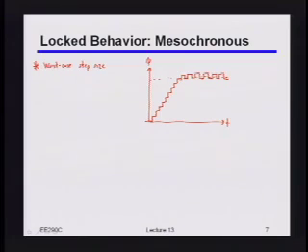You don't necessarily have a ton of control over that. I guess you could change the rate at which you're running the loop and things like that. But that dither has to be there, and in this particular context, it probably doesn't change the overall performance all that much. Maybe there are some second order effects in terms of the jitter filtering, but largely speaking, I pretty much have to be jumping up and down every cycle, because if I'm not, then things are even worse.